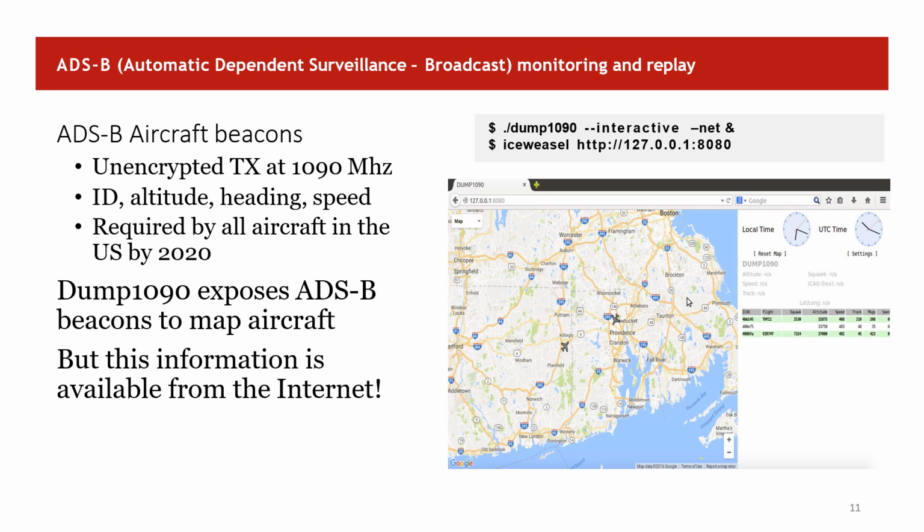And another thing is why this ADS-B protocol is used. This particular protocol is used by autopilots. When an aircraft is on autopilot, this ADS-B transponder is used to transmit the data to other nearby aircraft so that they can automatically adjust their altitude and flight direction, so as to avoid collision.